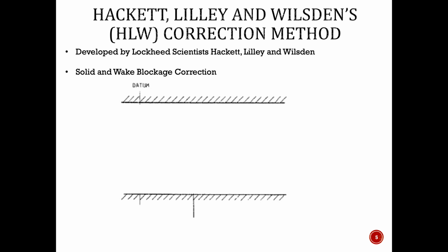This correction method was developed by Lockheed scientists Hackett, Lilly, and Wilson, back in 1975 or 76. It is primarily a solid and wake blockage correction that involves tunnel wall pressure measurements. Imagine you have an object in the test section, and of course you have a solid blockage, and you will also have a wake blockage. This is just a qualitative wake I drew here. Usually, depending on the Reynolds number, the wake can be either larger or thinner, based on what type of body you're looking at.